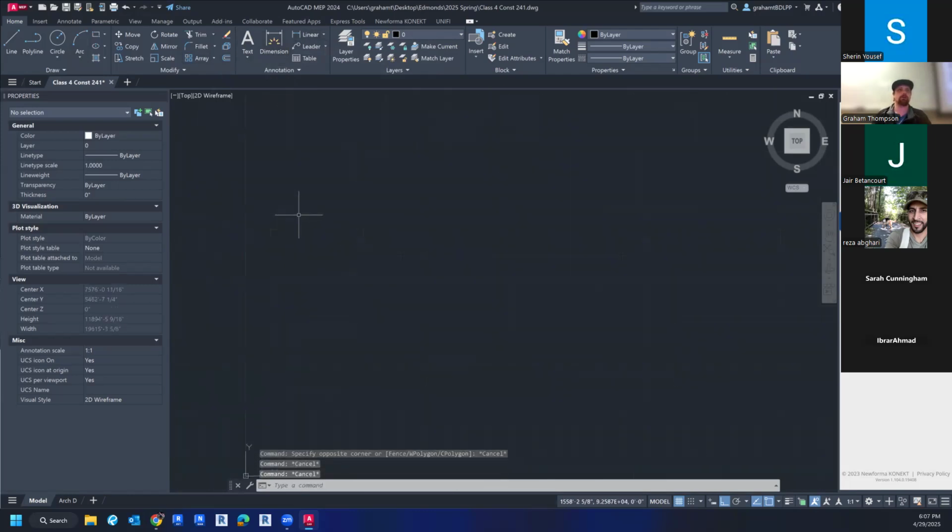And again, I don't care where you start in your drawing, but we're going to start by drawing a line. You can see right now I'm so far zoomed out that the line's almost 4,000 feet. So I'm just going to zoom in to where I want to, and I'm going to draw a line that's 40 feet long. I'm going to type in 40 feet into the command line down there, and that's going to give me a true 40-foot line.